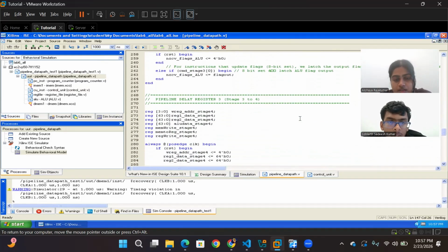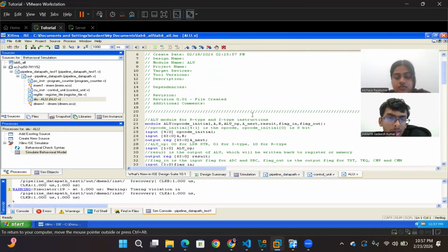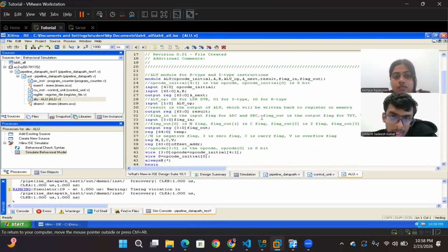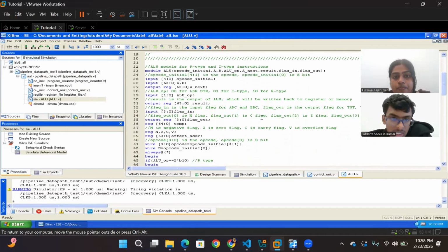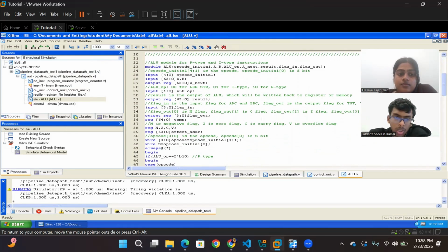Moving on to the ALU. For the ALU again, we stuck with the ARM ISA of course and designed our ALU based upon that. We didn't do much of a scale up from the initial ALU we developed, because again we want to stick with the ARM ISA. Based upon whatever opcode we got from the ARM ISA, for whatever functionality, we just built our own ALU on that.